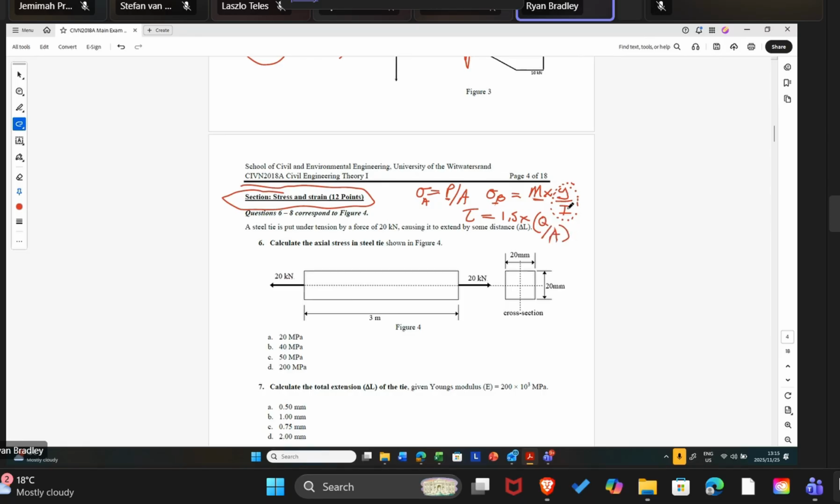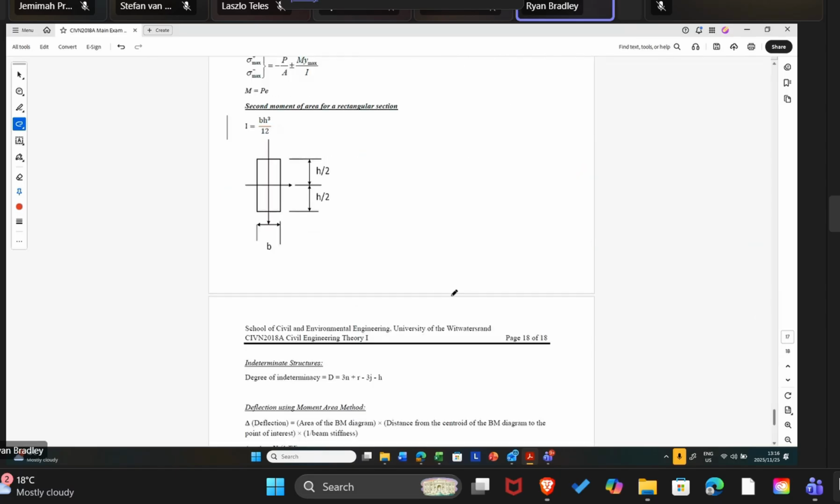So what you see here in converting from a force to a stress is that we are basically including a geometric parameter. For axial stress, it is the cross-sectional area. For shear stress, the cross-sectional area. For bending stress, it's this y over I parameter. Those are the fundamental equations for stress, and in your exam, you're given the equations. I'll just show you briefly what you might expect.